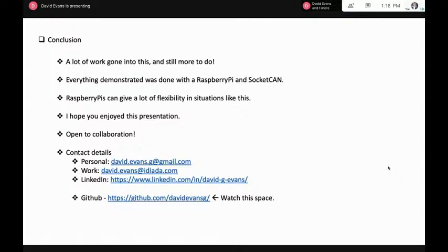So the next question comes from Raj. He's asking about encryption on CAN bus. Is that a thing? From my insight, I know it's a thing on future vehicles. I think some of the people in the comments are answering these questions as well. CAN bus encryption is a thing, but bus speeds struggle to support encryption over CAN bus. Do you want to talk a little bit about CAN bus encryption and automotive Ethernet and how that's playing into this?